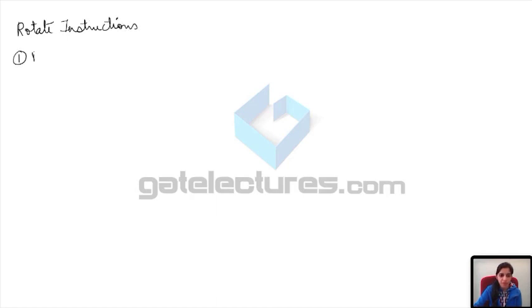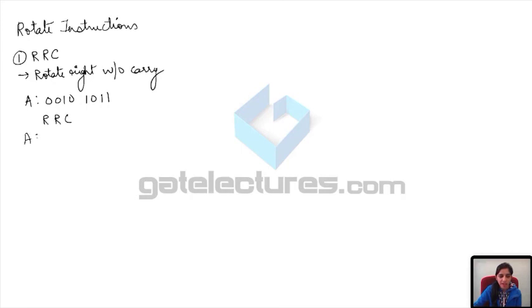The first instruction that we are going to look at is RRC, which is rotate right without carry. Suppose this was the content of the accumulator initially. After we execute RRC, the contents are rotated towards the right without carry. Without carry means whether the carry flag is 0 or 1, it does not affect this operation.